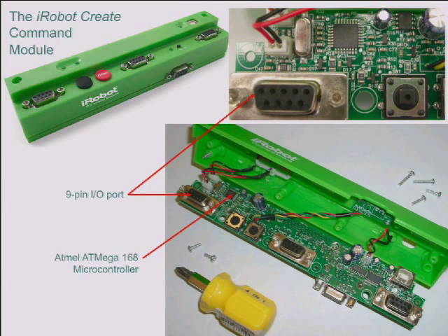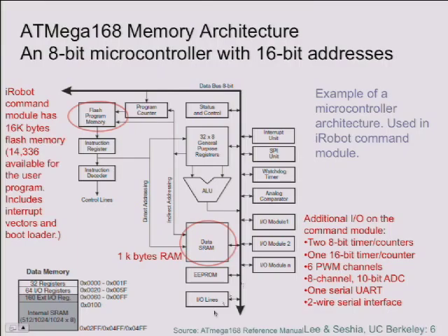All right, so this is about understanding the hardware. So the memory map is a big part of the hardware. This is the particular memory map here, and the way to read this is that the lowest 32 addresses don't refer to memory at all. They refer to the registers of the processor, okay? This includes the program counter, by the way.